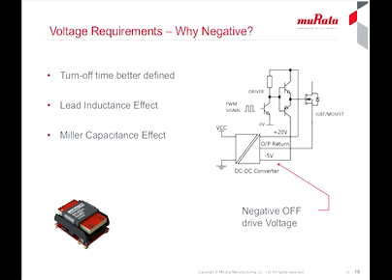Another condition is when the power switch circuit is not operating or is perhaps shut down in a load fault condition. In this case, the load on the DC-DC converter drops to near zero. This means that a DC-DC converter whose zero load voltages go very high is not suitable. When the load starts operating, these high voltages could cause stress to the gate until they drop to their correct operating value. The MGJ series of converters all have clamped output voltages so that at no load they are limited to safe values.